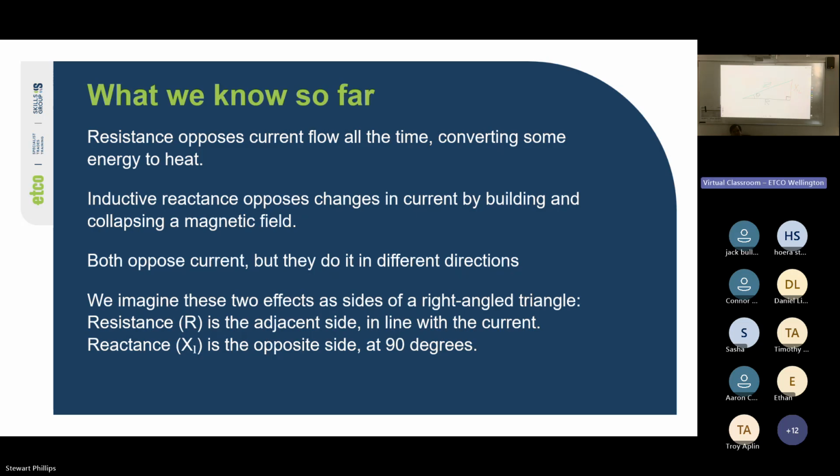Because it is impedance and not resistance, it changes the equation. So remember, whenever you're doing earth loop impedance, you're measuring it all the way back to the transformer and then all the way back to you along the neutral and phase conductors.